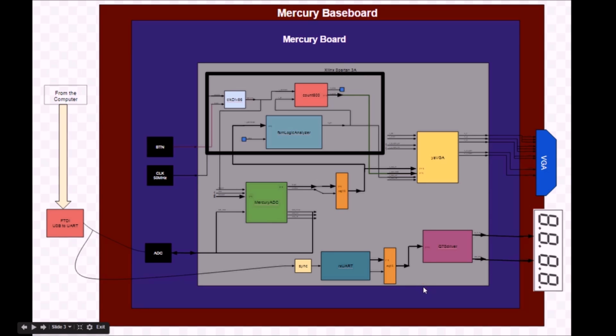Take our oscilloscope example. We have our own drivers for the SPI protocol, a VGA protocol, and we created a driver for receiving UART. 3 protocols being handled simultaneously with ease by the FPGA. Then we drive a set of 4 7-segment displays with a small bit of logic up here. The crazy thing is that we barely took up any space on the Spartan 3A with this application, and you could easily just create multiple instances of this top level and have multiple oscilloscopes running in parallel with no caveats. The only limitation that you have is when you run out of lookup tables on the FPGA.